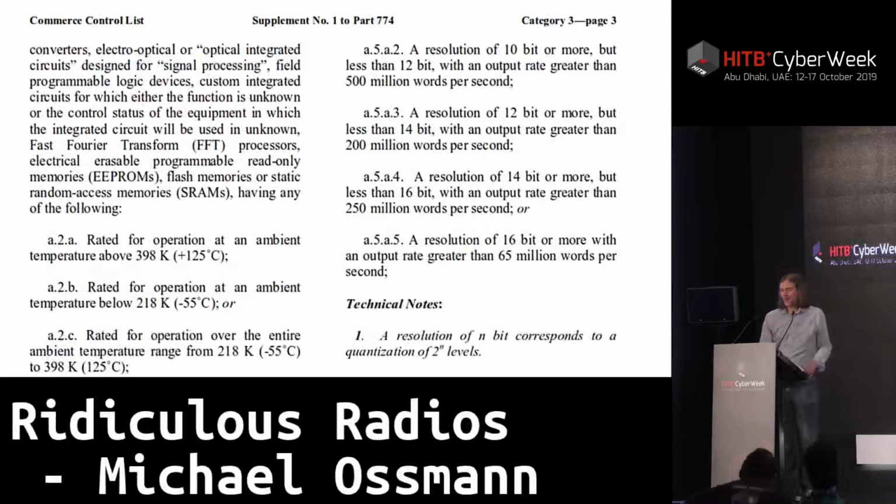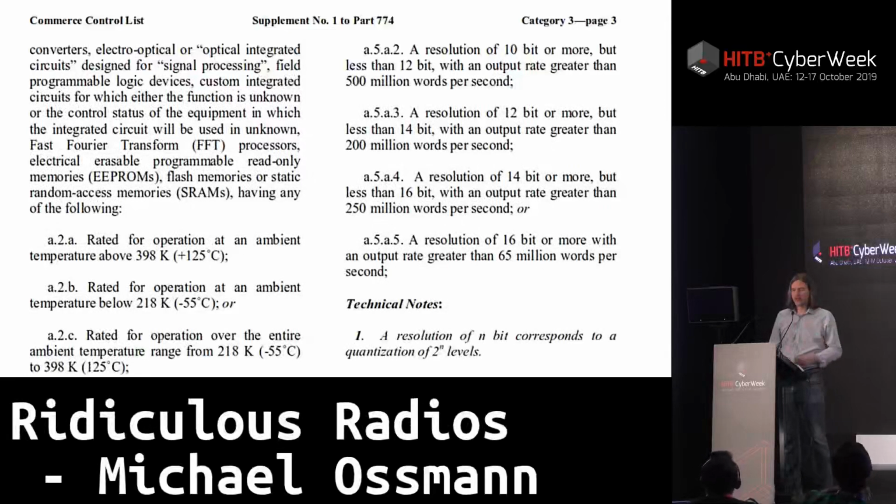So what if we could use a digital input, because we don't have an analog to digital converter on our microcontroller? What if we could use a digital input to implement a radio receiver? We put some thought into this, and we thought we should be able to do it. But the key thing we needed to realize was that we weren't going to get very good dynamic range. We weren't going to be able to pick up very weak signals.